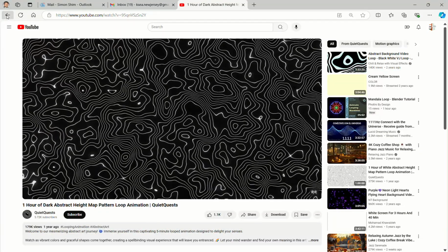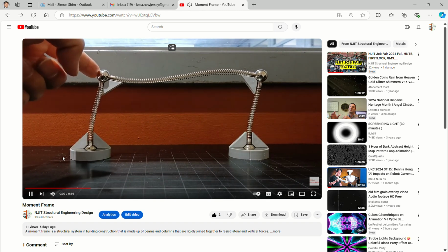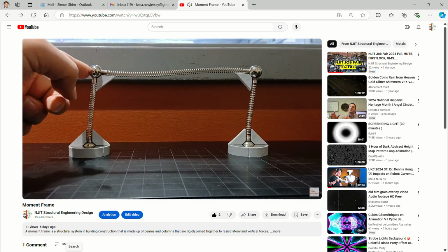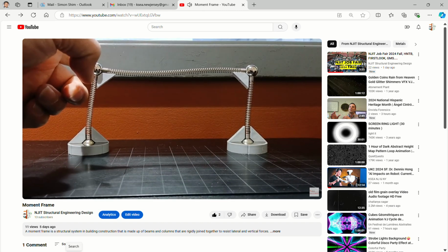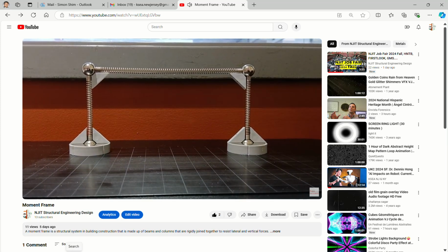Going back, I think we maybe can generate something else for the column too. But see this curvature on the beam because this is a connection. Also, you have some double curvature, right? This is a fixed or rigid condition, so you have double curvature, double curve deformation, because we have rigid connections.